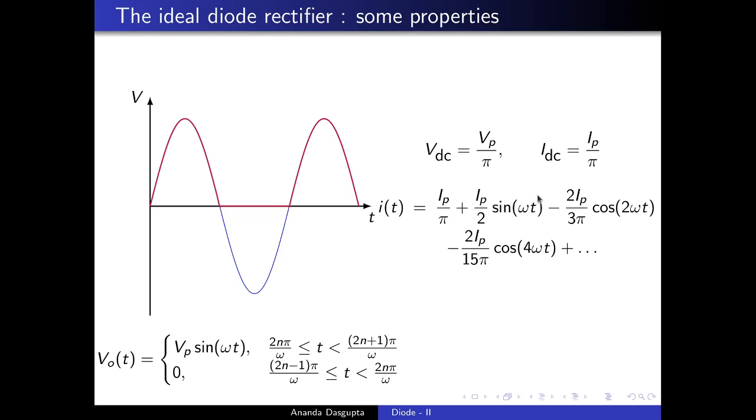In addition, you have one sinusoidal term and a bunch of cosinusoidal terms of different frequencies. These are, of course, all terms which go in both directions, positive and negative. The overall voltage doesn't, because of this average value which pushes the whole thing up. So, although the overall voltage goes in only one direction, it really has a substantial amount of alternating signal in it.